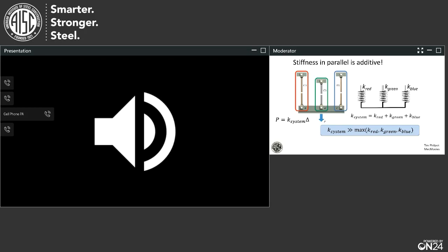I think my rule of thumb would be if it's a rigid connection, a moment resisting connection, a full restraint connection, and it's been designed that way, then I'm going to model it as a rigid connection in my analysis. If it's on the other extreme, the moments aren't necessarily being designed for, just the axial forces and the shear, then I'm going to model it as a pin.